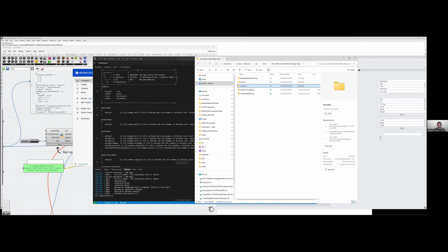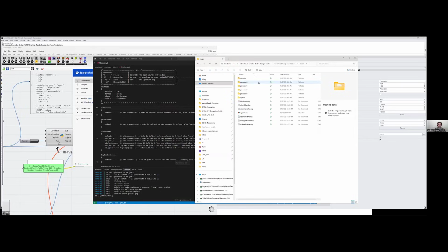And I want to show you how it should look. This is not a product of this simulation, but I just want to show you how it creates it. So you should have, and this is a done project, this in meshing. It will create all these dictionaries that you would need for your systems, for the mesh quality, for decompose, or if you want to parallelize it, or block mesh and so on.